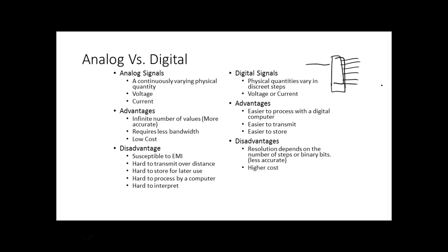Does that make sense? If we had a 10-bit A to D converter, that means we could only split the input into 1,024 different numbers, and there's nothing in between. So there's no such thing as a fraction. Does that make sense? Yeah. So if I was bringing 10 volts in, and I'm getting binary out, or 1,024 combinations, that would be what we call our volts per step. And there would be no fractions.